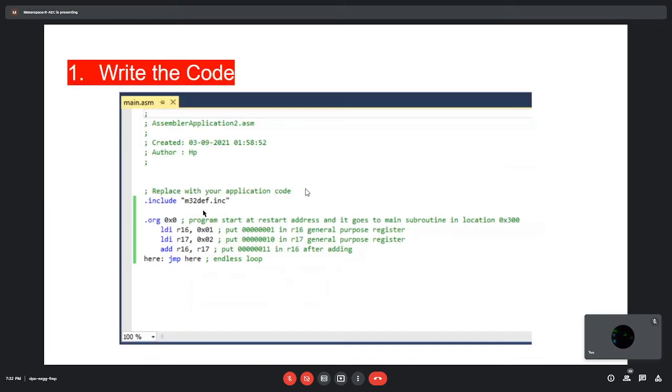So write the code. First we write it. It is just style. It's an assembly code, so it has .include, the M32 dev file, then .org, then add here, jump here. This is an endless loop. So we write this program.